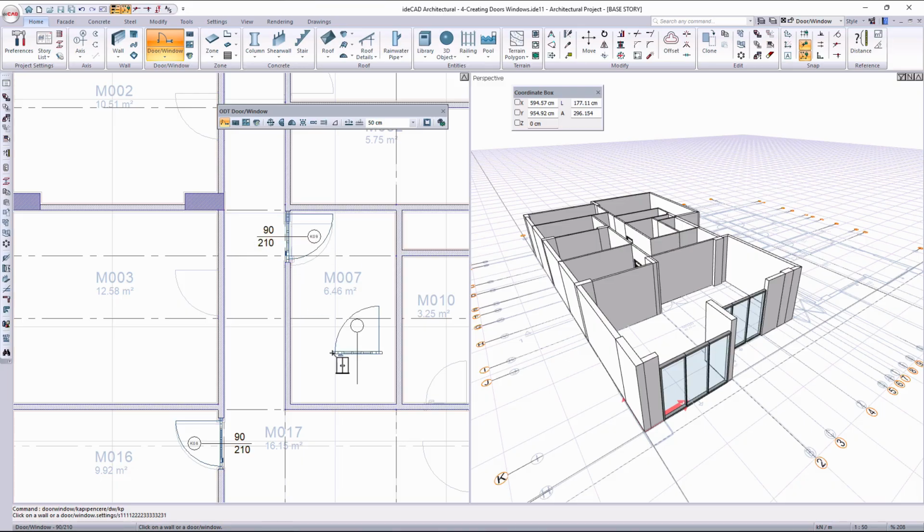Typically, when positioning doors and windows, a reference point on the wall is used to ensure accurate placement. The distance box on the toolbar determines how far the door or window is placed from the chosen reference point. When the Use Distance option is activated, the object will be automatically positioned based on the entered value, ensuring accurate placement.